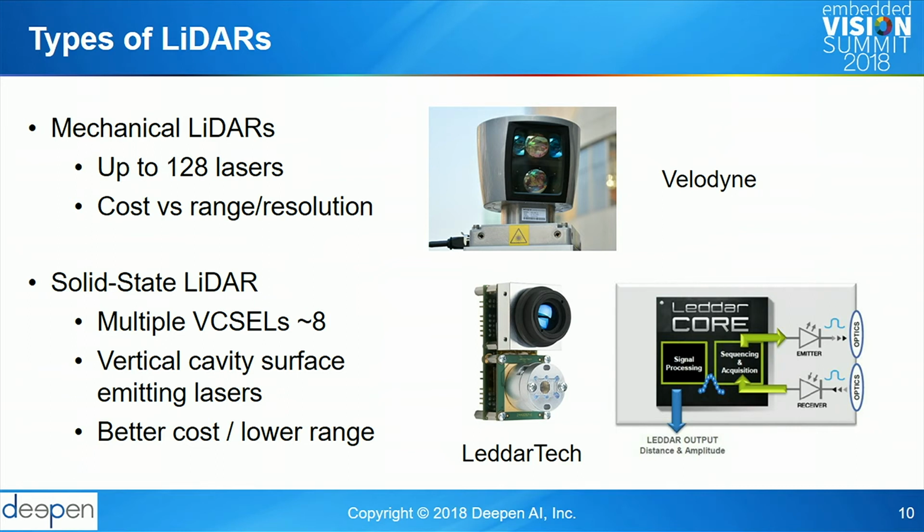But we've seen in our tools, when we help our customers with LiDAR data, if the car is moving and there is a very close object to you, in a mechanical LiDAR, you start getting a lot of ghost points, where in the multiple spins, multiple reflections of light start showing up for the same car in multiple places. So instead of getting a point cloud that has a certain location for the entire car, you get this car and another ghost behind it and another ghost behind it. And that ghosting is just a function of the frame rate and the fidelity or the wavelength of the LiDAR laser that you're using.